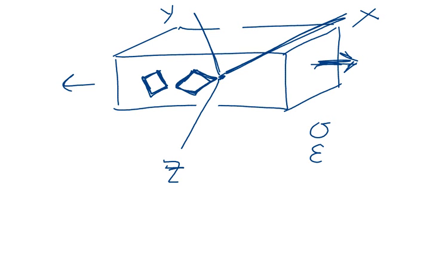It doesn't matter how you define your coordinate axes, really. The stress that you get from one set of coordinate axes should be equivalent to the stresses you get by using a different set of coordinate axes. The values are going to be different, but they equate to the same state of stress, as we call it. Remember we had this idea of a general state of stress.